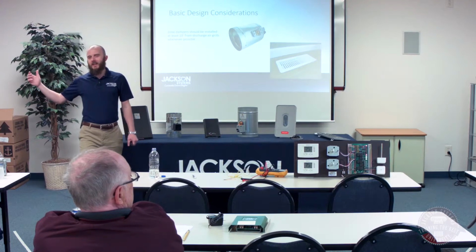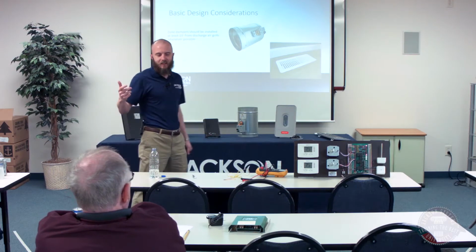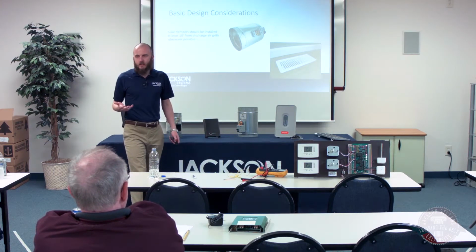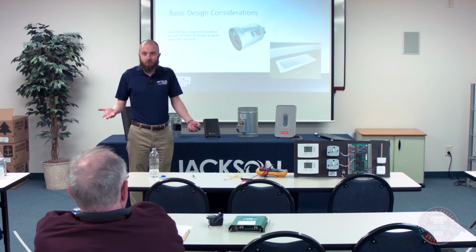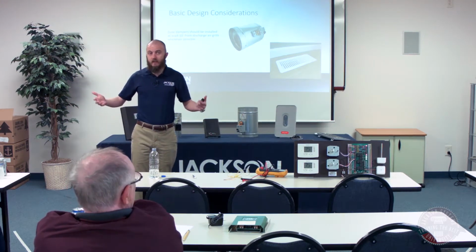Oh, okay. So if your damper's too close to the register, then you could have some noise at that register, which is going to cause customer complaints. Even if it's not a problem for temperature comfort, or anything else, noise can be one of the first things that causes customer complaints. Zone dampers should be located where they can be accessed for troubleshooting.